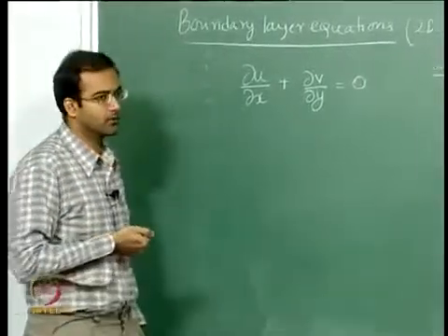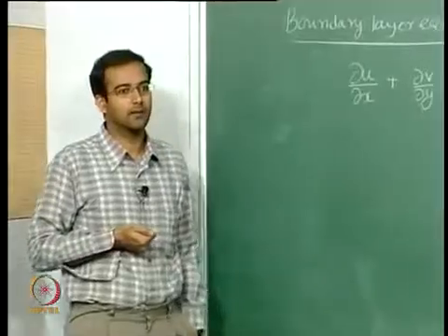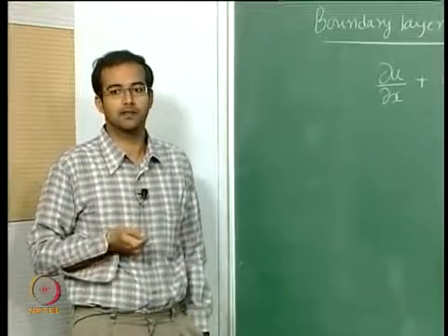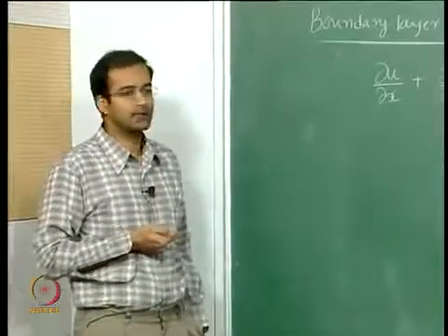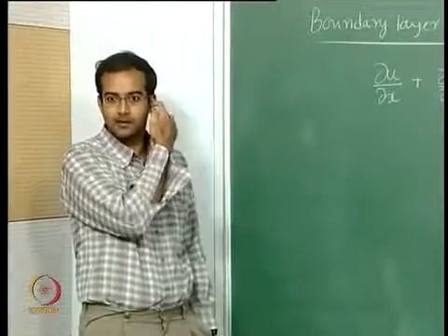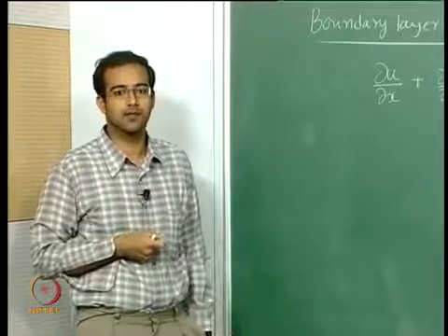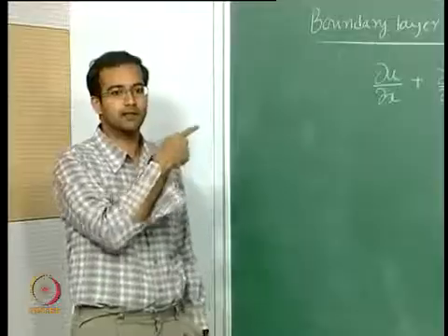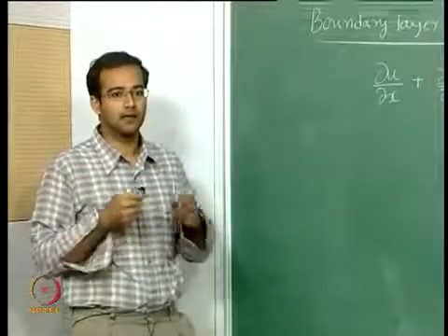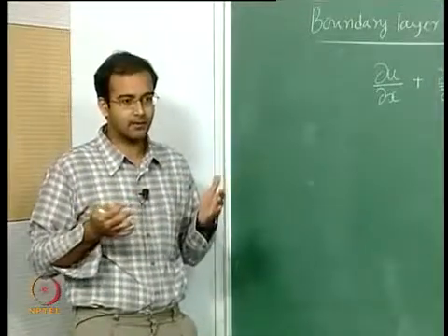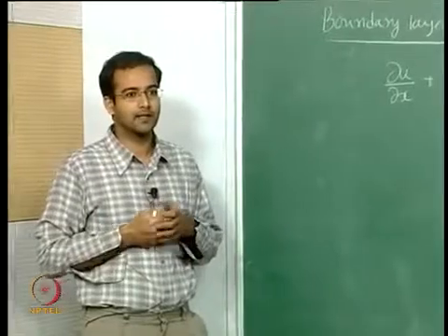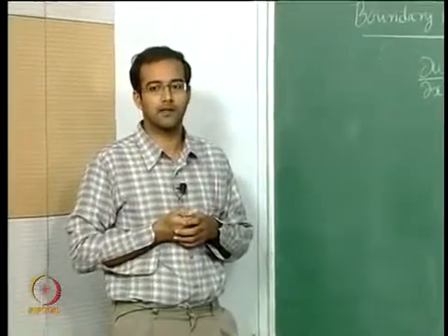So in order to model turbulent flows, we construct what are called Reynolds averaged Navier-Stokes equations. We average the equations that we have, and we can do different kinds of averaging. Of course, for steady state it doesn't matter, we have an ensemble average.